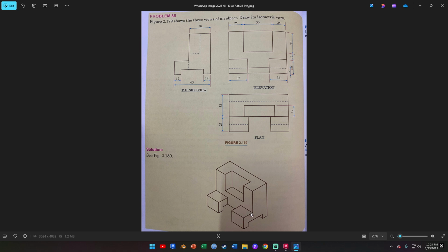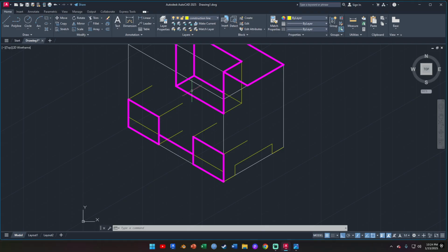We already came in 25 mm here, so we can finish off this side here. And we pretty much have the end view here. So what we could do, we could actually draw the outline. So you can switch to outline, click on line, and we can complete our end view here.